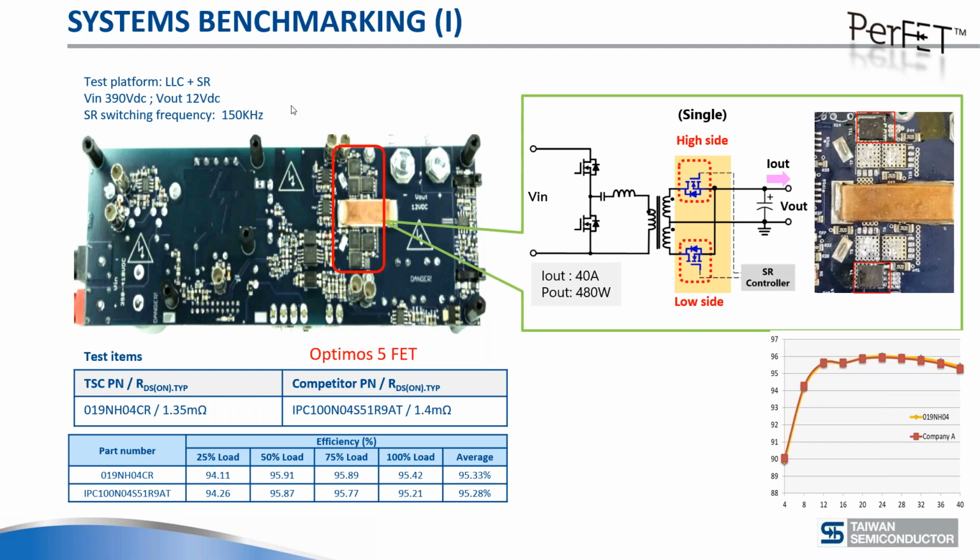So what you can see here is that against this OPTIMOS 5 product, the efficiency is actually quite similar. We measure the efficiency at 100% load, but sometimes, as you know, as we are speaking at the moment, or when you're typing your emails, you're only using your computer at a fraction of the top power capability. You're going to use the top power, the 100% load, if you're playing video games or something like that.